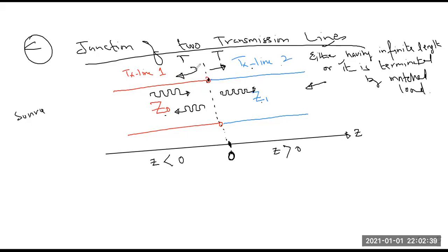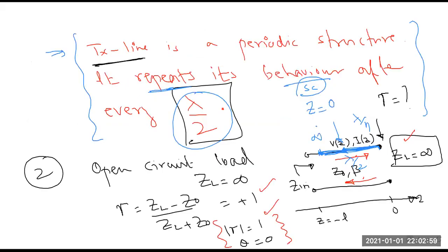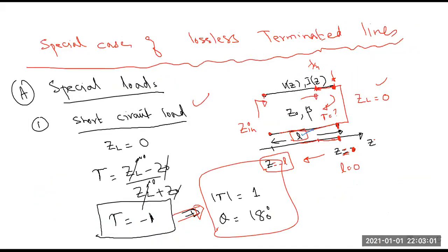How much is going to be reflected? That is calculated based on the result that we have been using, Z1 minus Z0 over Z1 plus Z0. In this case, Z1 is acting as a load. Just like the standard equation, let me go back. I used it somewhere here.